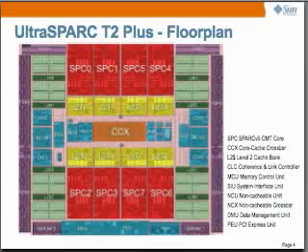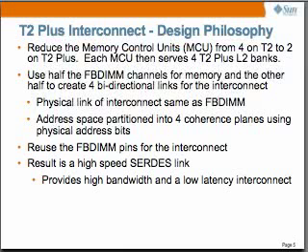I would say the heart of this design, the novel thing in this design, is the cache coherence. For that, we reduced the number of memory control units from 4 to 2, and we use those two to implement the cache coherence. We can use the same interconnect, so that's good. And we introduced 4 coherence planes across the system to maintain that coherence.